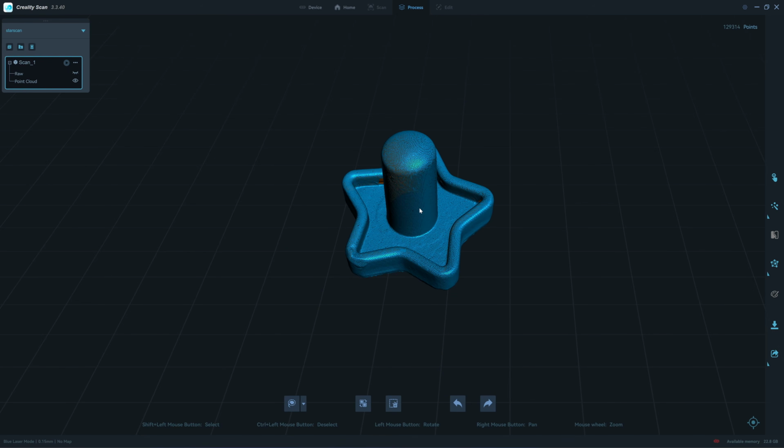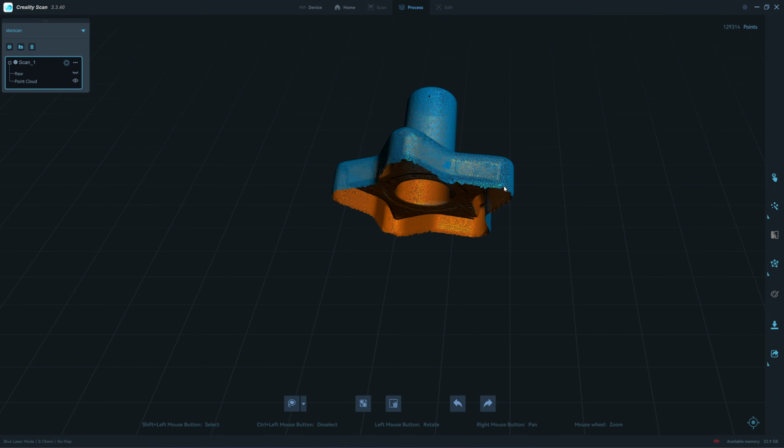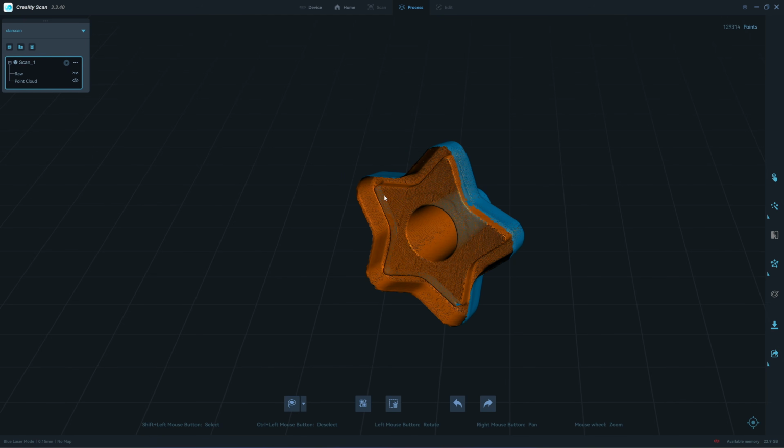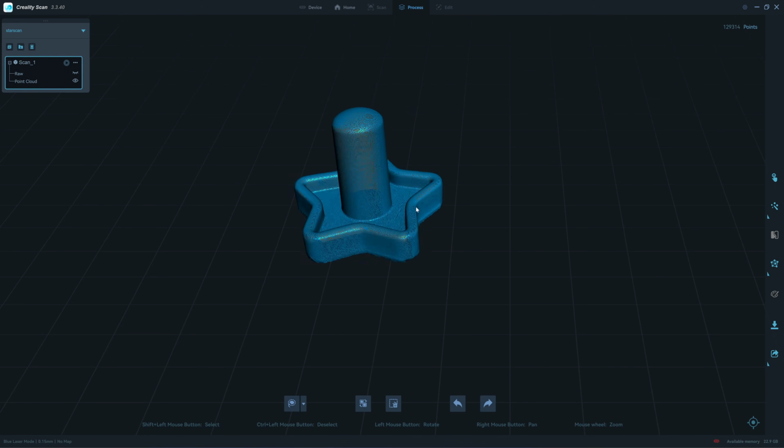The best practice for reversing is using the point cloud, because you will be able to clearly see the wall of the surface, and you can trace it with higher precision than you can with the mesh, especially in FreeCAD. And the bottom side of this object is just a flat plane, so it's not necessary to make a second scan. This will be enough for reversing.